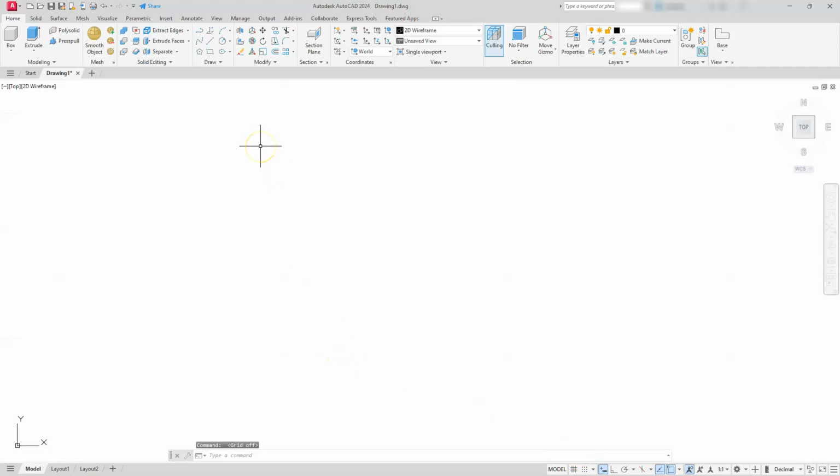All right, I'm just going to create a line, and if you're not familiar or you like to use the ribbons at the top, I will show you where they are, but it's always a lot simpler in AutoCAD. Just hit L and hit enter. But the line command is located here. I'm going to select that. I'll click my first point.